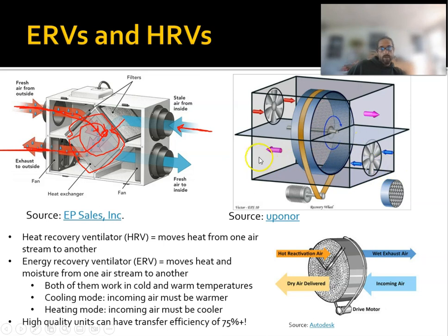Okay, it dumps moisture into the air going out, which dehumidifies the air. So an ERV will preheat air in the winter and pre-cool air in the summer for ventilation. And the ERV, what did I say? The HRV does that. The ERV does both humidity and temperature. So it evens out. So it dehumidifies warm, moist outdoor air, and it'll actually add moisture to cool winter air, which helps because then the building's not too dry.